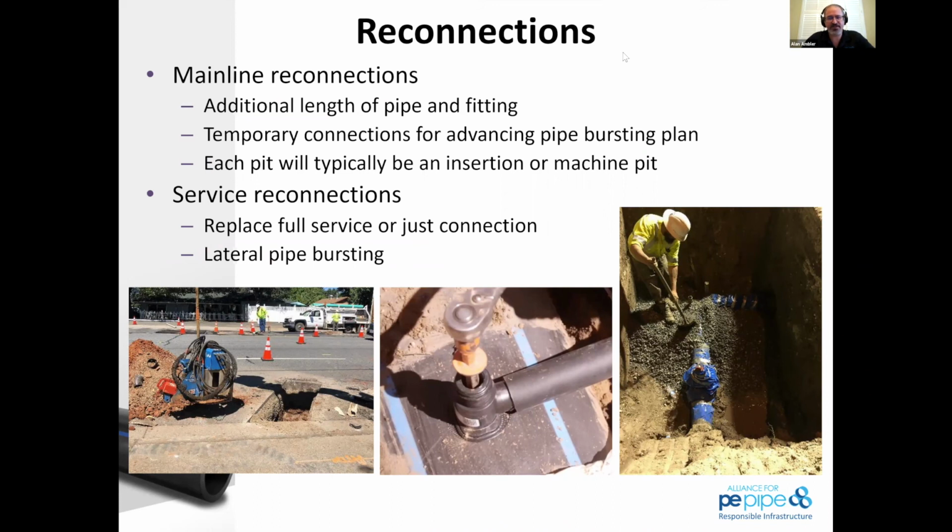Necessity is the mother of invention, and being involved in this industry for a while now, I've seen so much growth and development over the past 10, 15 years, as Matt really indicated here. So the available tools for you for even valve connections, AVK, one of the members of the Alliance for PE Pipe, actually has a ductile iron valve that has a polyethylene stub out that's forcibly pushed on a ductile iron or metallic piece with several lips that holds this polyethylene in place.